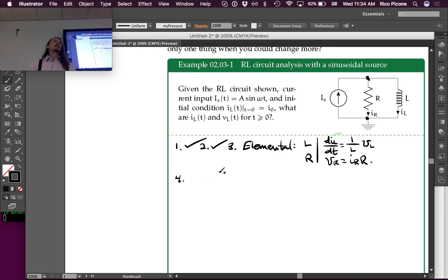Step 4. Finding the KCL equations. And this actually shows you a little bit of a weakness. Remember I told you that this systematic approach works most of the time, but you might have to write an extra KCL equation or a KVL equation, or one less than the rules prescribe in a given situation. This is one of those cases. There are 2 nodes that are not connected to a voltage source in this circuit. There's this node up here, and there's this node down here, which encompasses, of course, all of this wire, each node does.